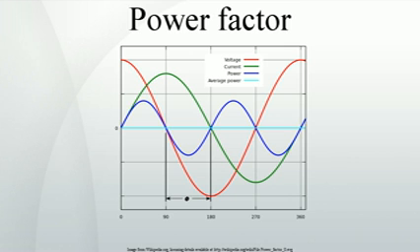This simplification is often a good approximation for stiff voltage sources, not being affected by changes in load downstream in the distribution network. Total harmonic distortion of typical generators from current distortion in the network is on the order of 1 to 2%, which can have larger scale implications but can be ignored in common practice. The result when multiplied with the displacement power factor, dPF, is the overall, true power factor or just power factor, PF.